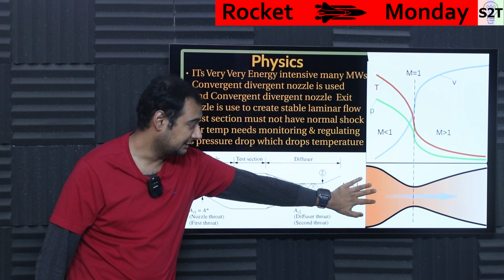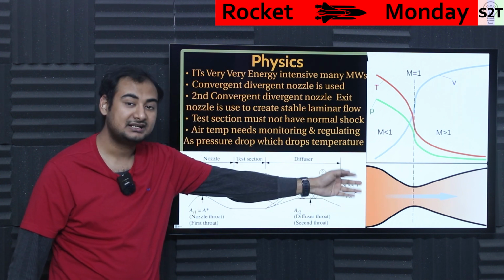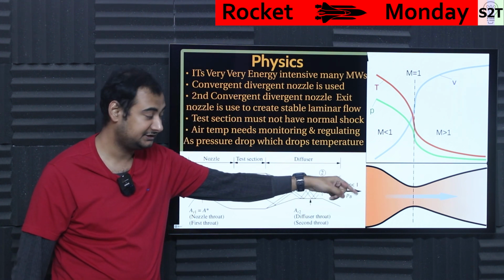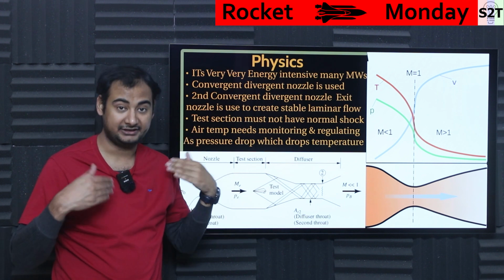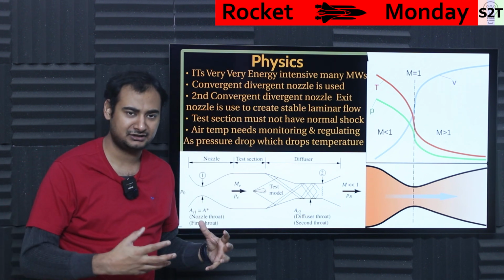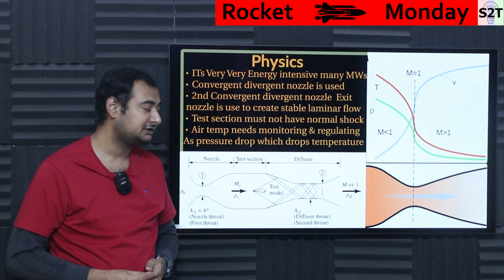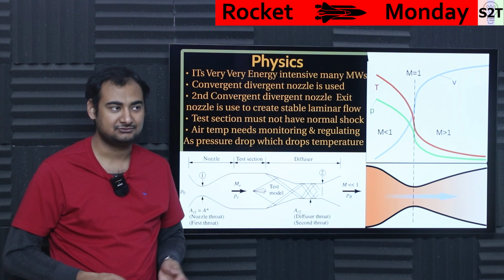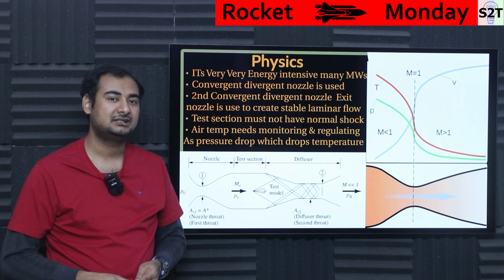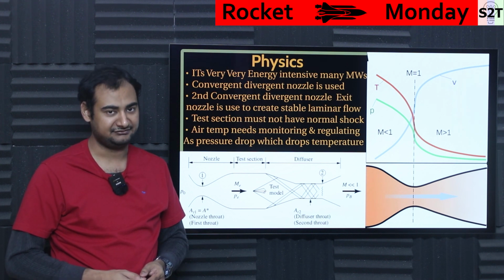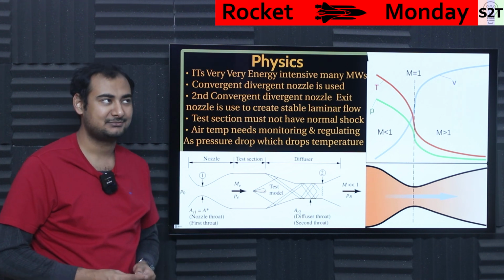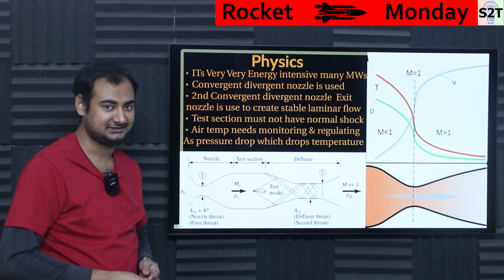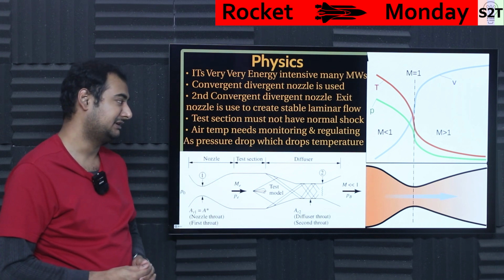is taking high pressure and high temperature air and expanding it, meaning it will cool down. If you try to go very extreme and you're like, oh, I'm going to send very high pressure air and I want hypersonic speed on the other end, you're not going to get anything. You're going to get vacuum on the other end. It's like, how the heck did you get vacuum? Well, the temperature dropped so much that the air condensed, meaning you're going to have liquid nitrogen and carbon dioxide and liquid oxygen at the other end. So the temperature has to be managed.